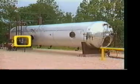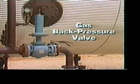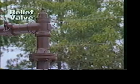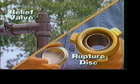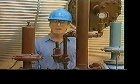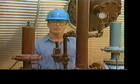On the gas outlet line, the gas back pressure valve maintains enough pressure in the vessel to dump liquids. The safety device may be a relief valve, rupture disc, or both. They are designed to open or burst if too much pressure builds up in the treater. Some heater treaters may have a make-up gas line with a regulator to maintain the proper operating pressure of the unit.